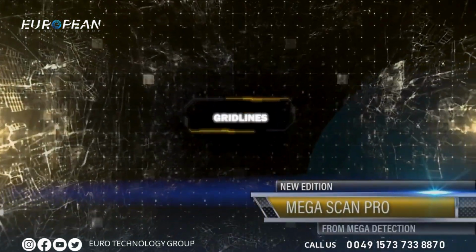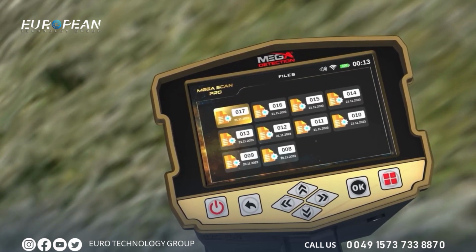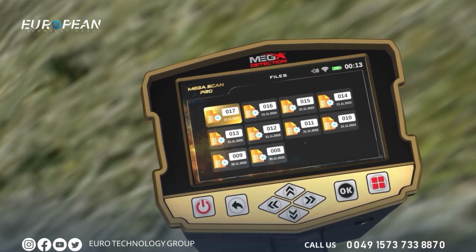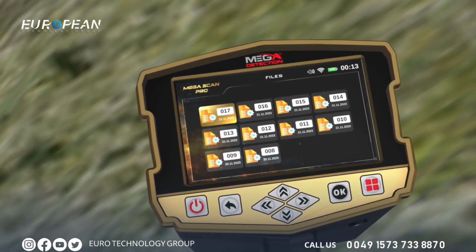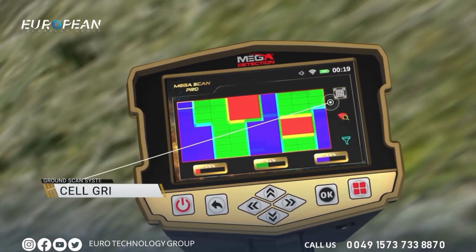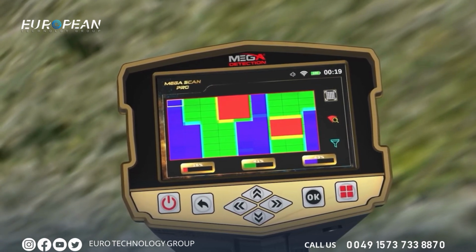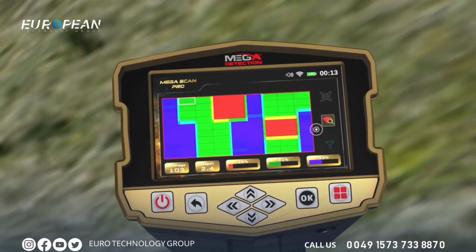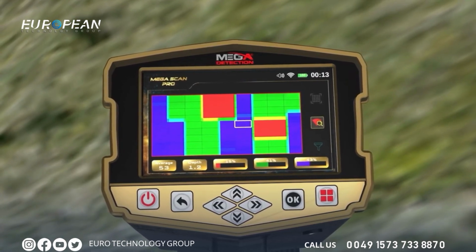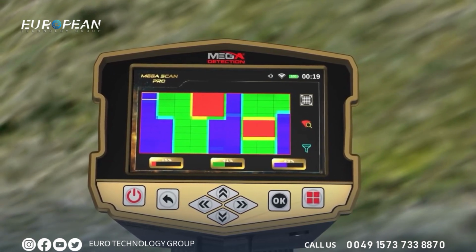Grid lines. This option shows or hides the grid lines that represent the scanning area, where each cell represents one scanning step. Scan point. Choose a cell from the grid. Use this option to select a specific cell from the scanning area grid within the scanning results screen. After clicking on the search icon, use the arrow buttons on the button board to select a specific cell. To return to the scanning tools, press the back button.